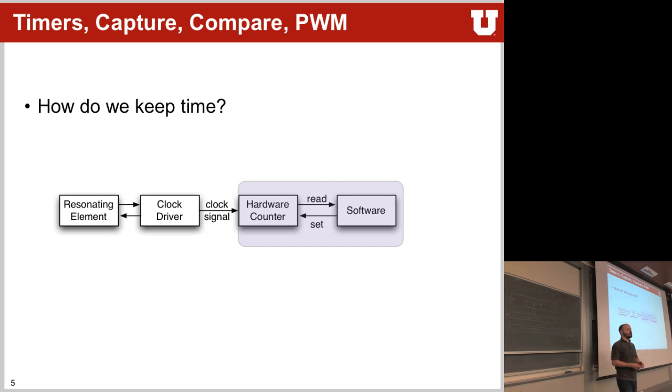So what could you use a compare for? Loop counters? Yes? Pulse width modulation? Scheduling an event, exactly, right? Scheduling an event, it would generate an interrupt to your software, and you can do something at that particular time. PWMs are very important utilities. Oftentimes there, you actually use 2 compare registers. So does everybody know what the PWM signal is?